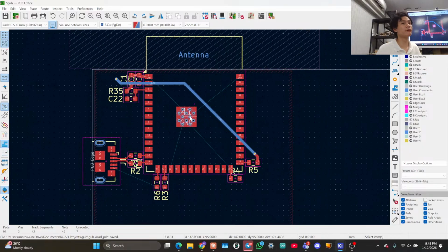Does this make sense to everyone? What we're doing? So this is how we cross wires over each other. If we only had one layer, this would be impossible. So we have more than one layer, and now we can just have wires on different layers, and then they can cross over each other, and we can have much more flexibility with wiring things. Make sense?